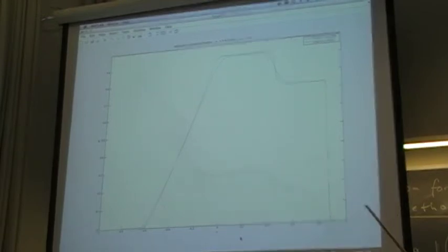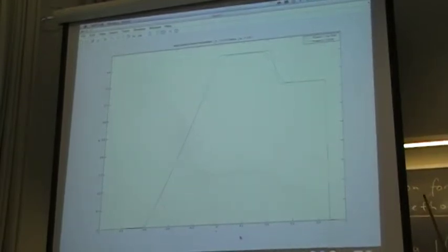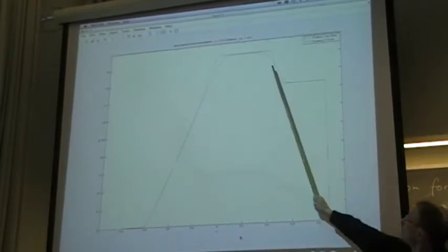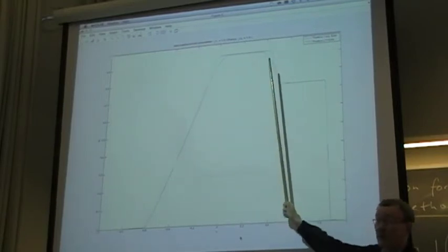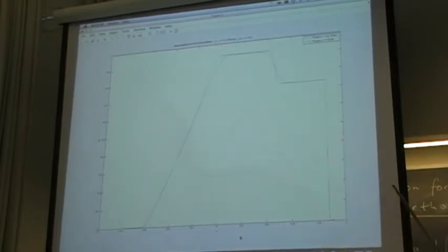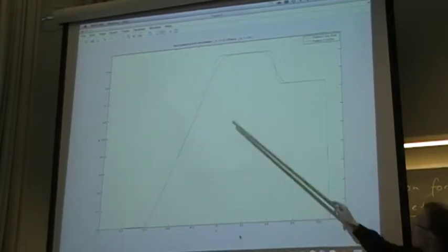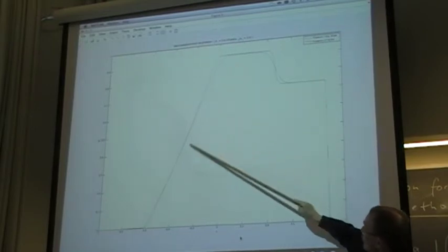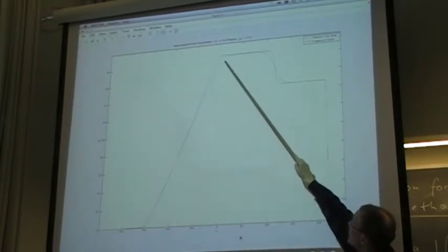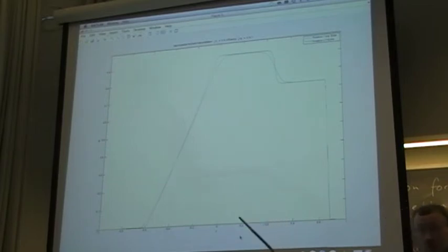That is the discontinuity which is the difference between the fluids. If we had helium on the left and air on the right, that would be the location. So we get more accurate results with MUSCL here, and also the expansion fan or reflection wave is resolved better with the MUSCL approach.